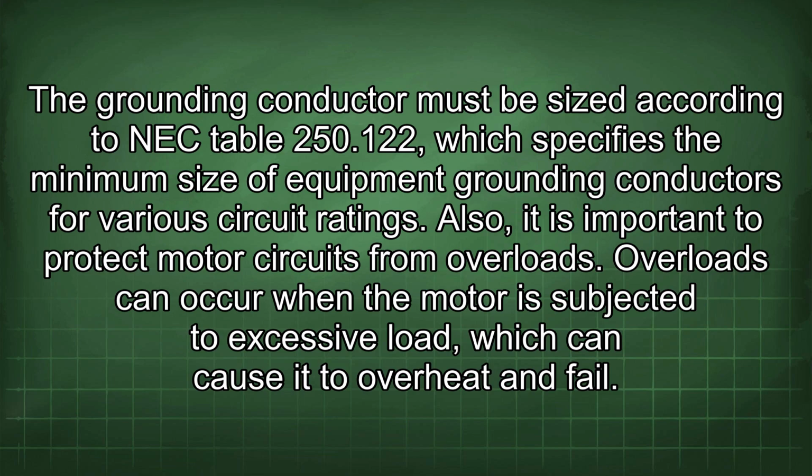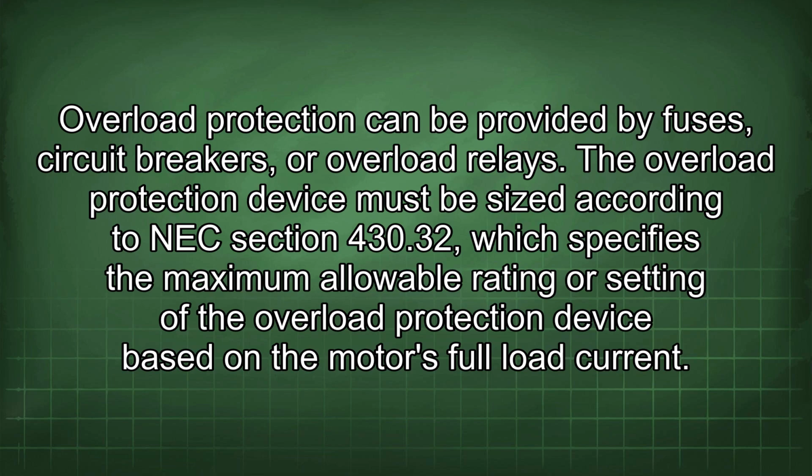Also, it is important to protect motor circuits from overloads. Overloads can occur when the motor is subjected to excessive load, which can cause it to overheat and fail. Overload protection can be provided by fuses, circuit breakers, or overload relays. The overload protection device must be sized according to NEC Section 430.32, which specifies the maximum allowable rating or setting of the overload protection device based on the motor's full load current.